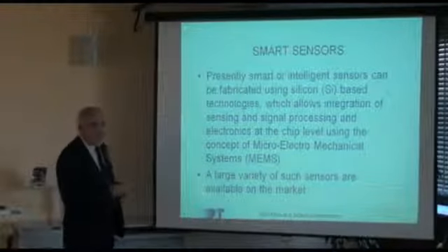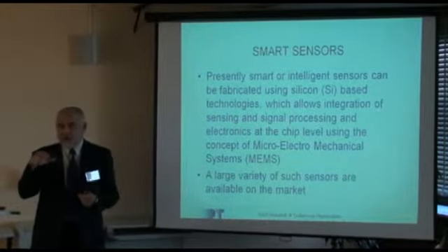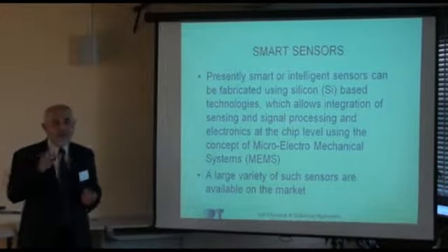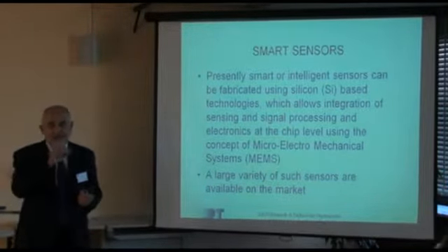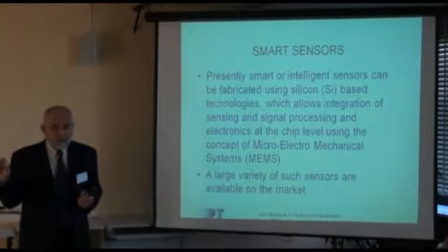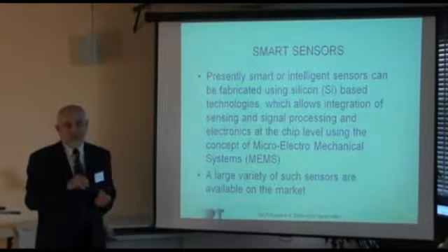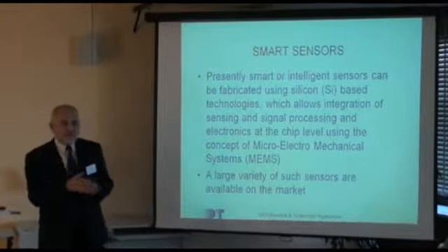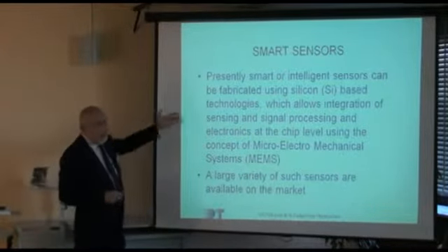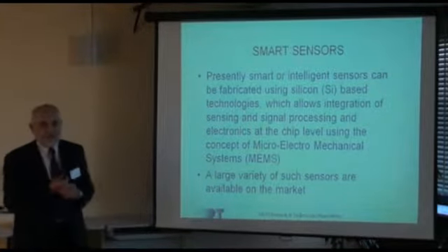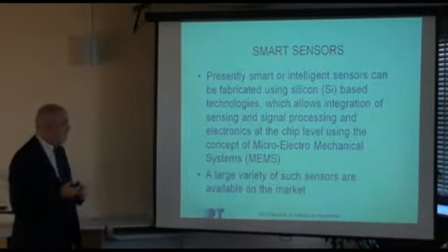Whereas in silicon on insulator, on top of that wafer, I have an insulator that is a glass, silicon oxide, and over the glass I have a very thin silicon that could be 200 nanometers or so. And the electronics is on that very fine sheet of silicon. So this is the point for which silicon on insulator is different as a technology.